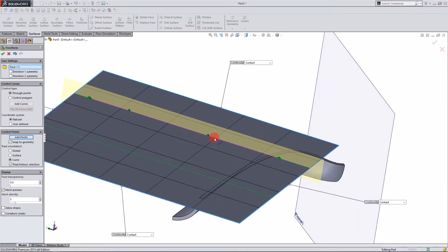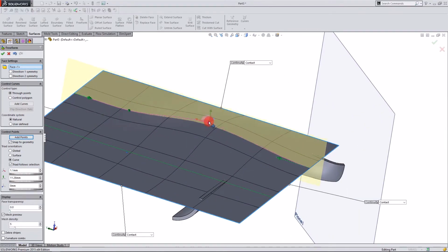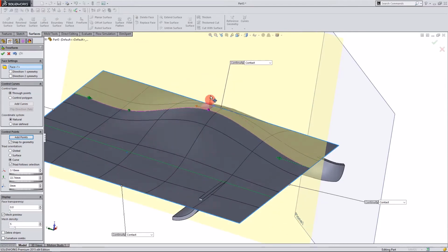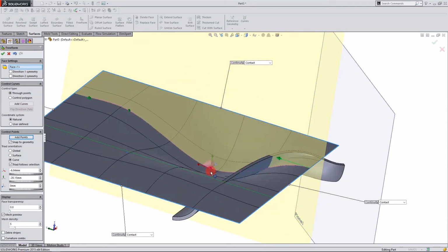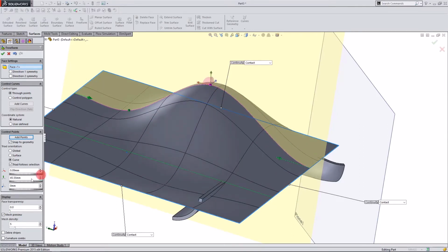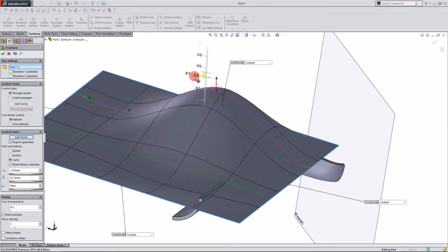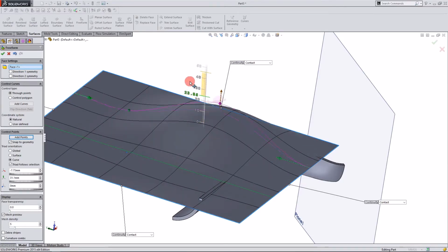So once I've created the curves, I can actually stretch the surface by hand amazingly. And so here it gives you the option of the dimension that you want to have for each of your triads in the X, Y, and Z direction. So I can manipulate this pretty much at my will, really in any direction I want.